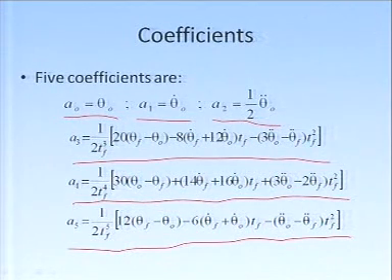So, now you have a 5th order polynomial which will satisfy all 6 conditions, which we call position conditions, velocity conditions and acceleration conditions. You might be asking why we are putting velocity and acceleration conditions. Sometimes, if you want a smooth motion, you want the velocity at the start and at the end to be 0. Assume that you are running and somebody just wanted to stop you. What will happen?